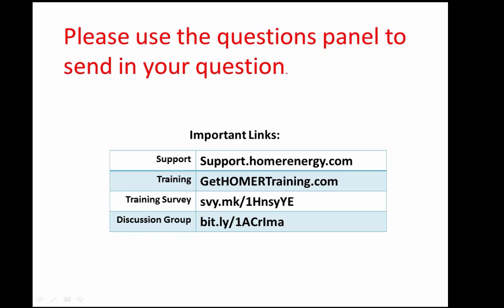Right. Wind data is so much more site-specific than solar data. So the NASA data will give you the seasonal profile. It'll give you some kind of average over an area, but especially if there's any complex topography, mountains or ridges or anything, it varies over very short distances. So you'd still want to do a sensitivity analysis, and if you're on the verge of making a significant investment, you probably want to actually measure, put up an anemometer and measure it.